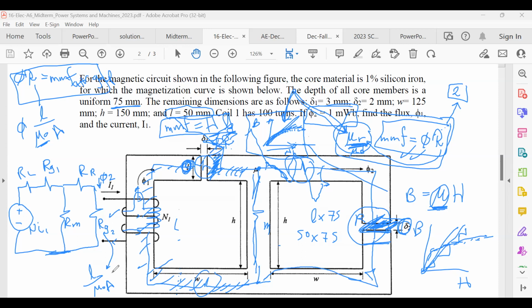So you have the reluctance and you have the flux. Can I get the MMF here? Or the voltage, similar to the voltage, right? The MMF here. Yes, as we said for the air gap, it's the flux times the reluctance. Then, can I get the MMF here? What is the MMF of this one? This is actually the one for the iron, for this iron part.